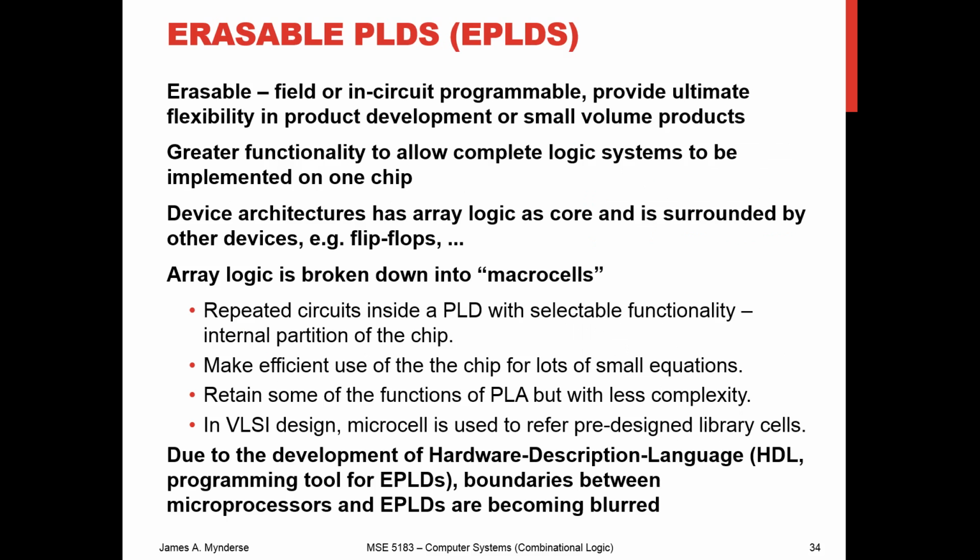Erasable PLDs, those are the ones that we can reprogram, typically a limited number of times, but still we can reprogram them. So we can use this logic as the core of our device and then add other stuff to it, kind of like our FPGAs. And then typically what will happen is this array logic is going to be in these macro cells, and then we'll reproduce this macro cell multiple times, which aids the programming, because if we know how to program one of those macro cells, certainly we can program all of them. And so for lots of small equations, we can make efficient use. If we had several really big equations, it might be a little more difficult.